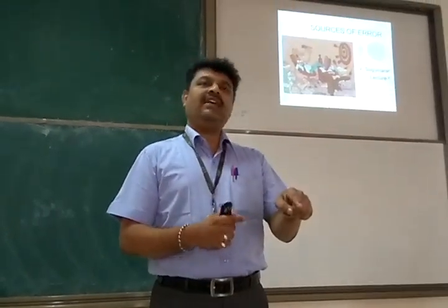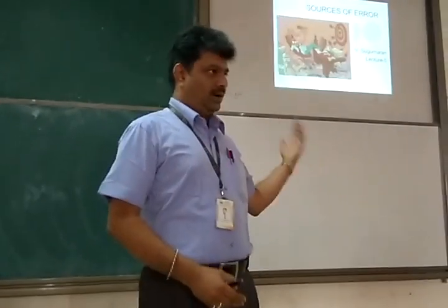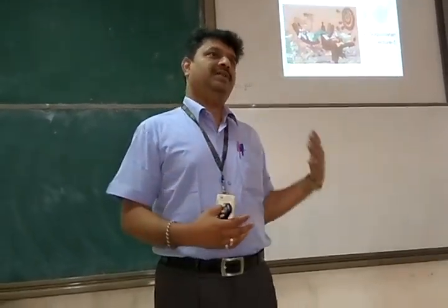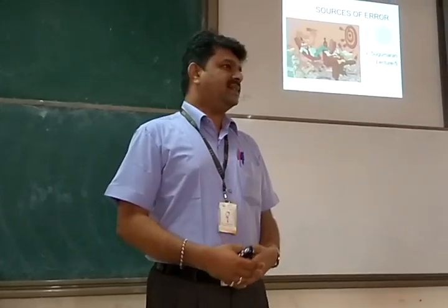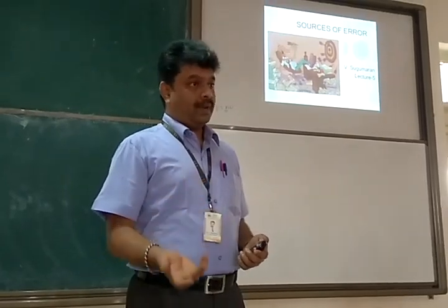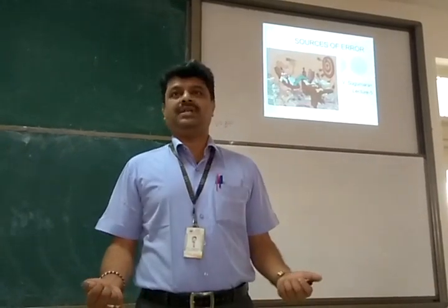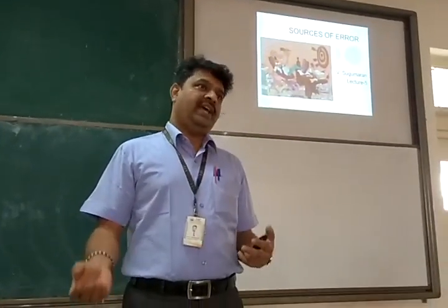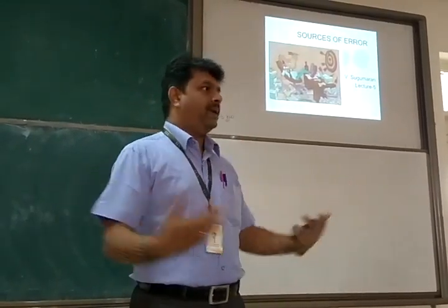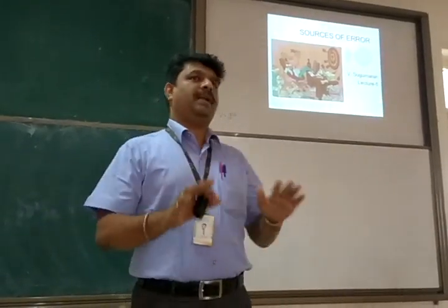If speed is having certain error, torque is having certain error, then power will have the compound error. Okay, how to compute the combined errors of the parameters of that sort. If I am only interested in speed, probably the case is a little simple because we need to quantify what is the error. When a parameter is computed from two parameters which are measured from instruments, each of them will have some error, and how they exhibit themselves in a formula, whether it is in denominator, whether it is in numerator, when parameters are getting added, when parameters are getting subtracted, how is their interaction? Okay. All those things we are planning to learn today.